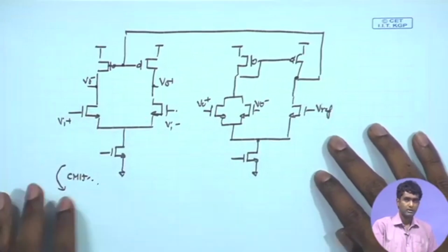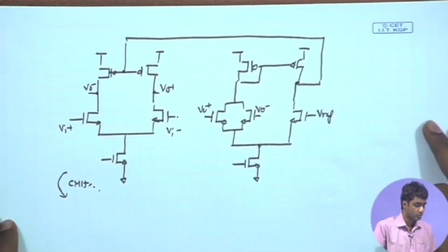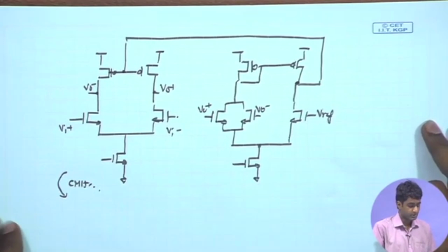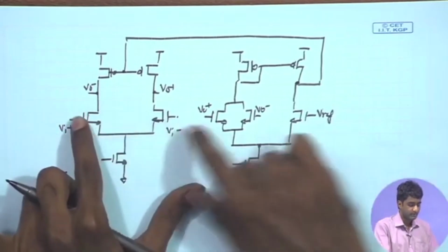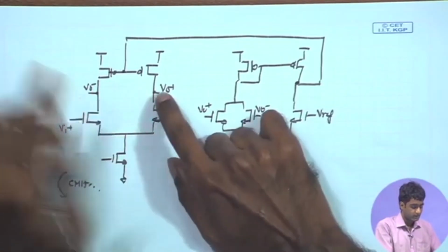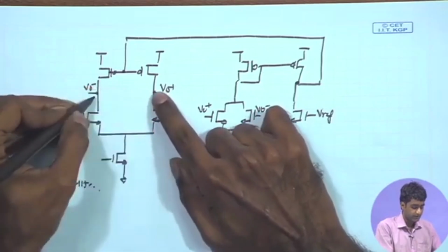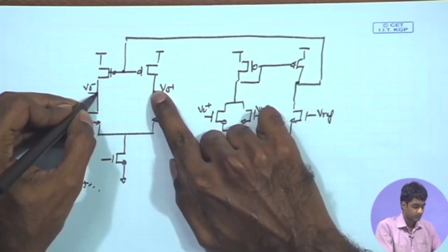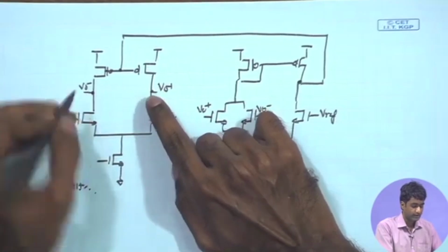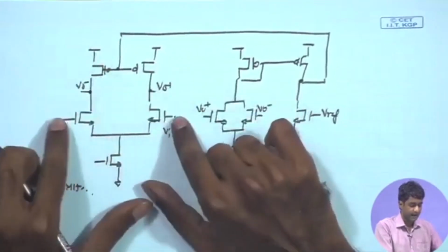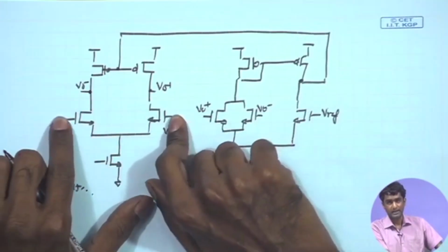And then we look at the common mode half circuit. So, if you are looking at common mode signal or common mode DC point, we said that these two drain potentials are going to be close together, they are going to be exactly the same if the transistors are matched and you have a common mode DC level applied over here.